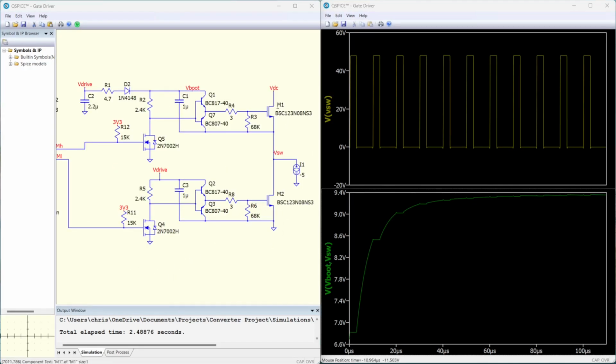In order to turn on the high-side MOSFET, a higher voltage than the input voltage is required. This is needed because when the high-side MOSFET is turned on, we almost have the input voltage at the switch node, disregarding the RDS(on) losses, which are very low. And therefore we need a higher voltage to have a positive gate-to-source voltage, turning the high-side MOSFET on. To get a higher voltage than the input voltage, a bootstrap circuit is used.